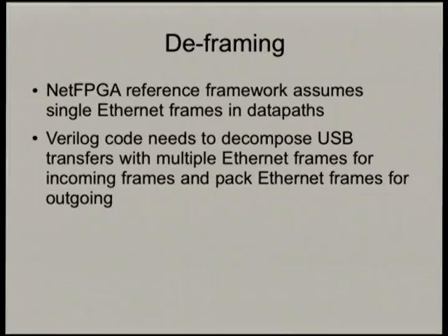The other thing that the Verilog code needs to do then is to deframe. So we can have up to 90 odd Ethernet frames packed into one USB 2 transfer. And so they need to be deframed once they hit the FPGA, because the FPGA is only dealing with Ethernet frames.